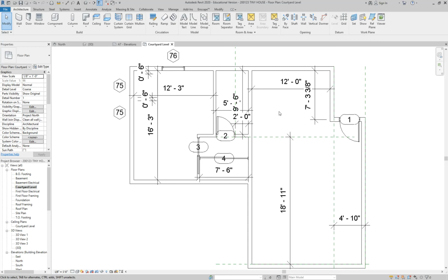A section actually cuts through a building. So imagine I have this giant saw and I'm cutting the building. So when I cut the building, not only do I see the interior corners, but I see the roof and ceiling above, and I also see the floors below. And since I slice those walls, now I can see the construction of those walls. They don't just look like solid walls like this, but I can see the drywall, the sheathing, the studs, and then the drywall, and maybe even the tile on the other side. So that's the difference between a section cut and an interior elevation.